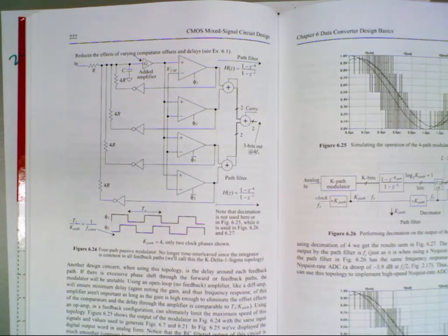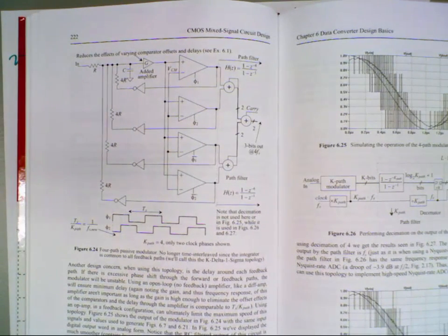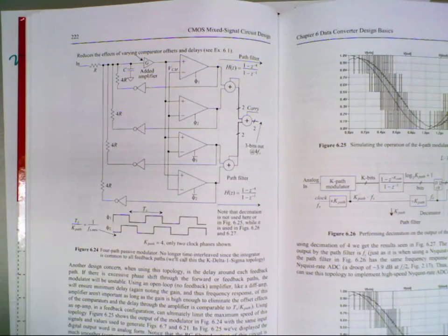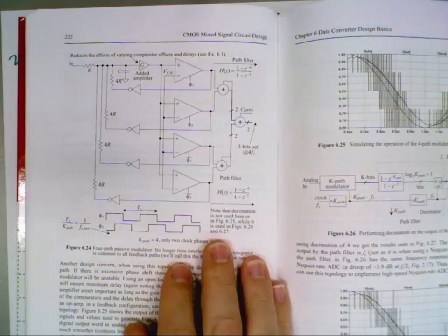Now, if you notice in the sims that I went over a moment ago, where I had all 8 bits in parallel, you can read those out in MATLAB and then read them out as though they're serial. So there's a way to trick it so that you can get really narrow high-speed bits out in a serializer, then basically treat them as though they're coming out serially and not parallel. Okay. Let's see what else here.